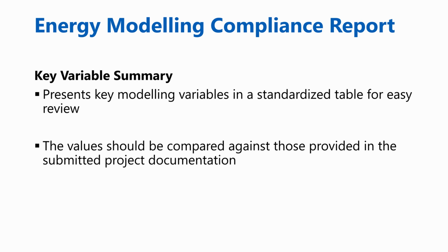So we got a peek at the energy modeling compliance report there, and we'll just talk about those elements before hopping back over to the tool. There are two main components to the compliance report, the first being the key variable summary. This presents key modeling variables in a standardized table for easy review. The values presented here should be compared against those provided in the submitted project documentation.